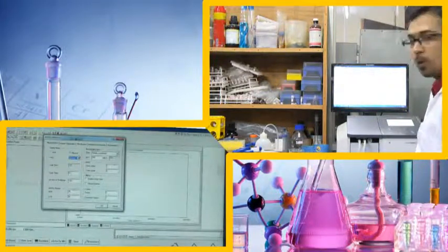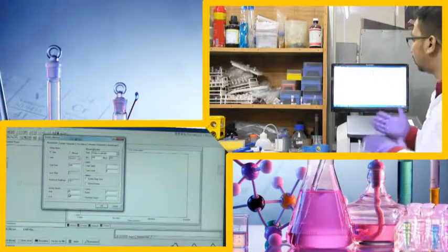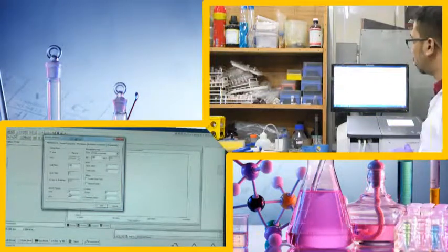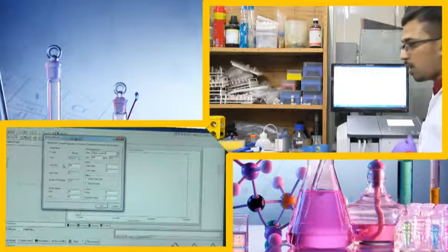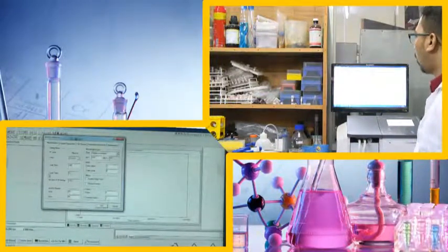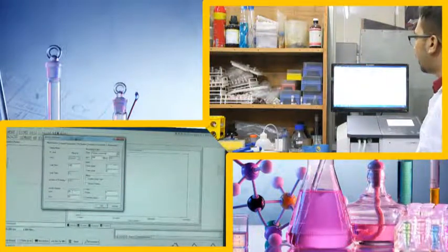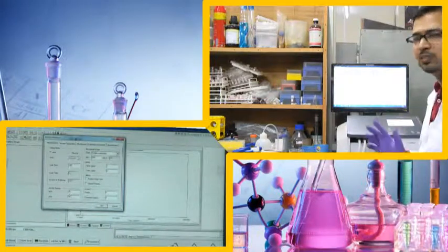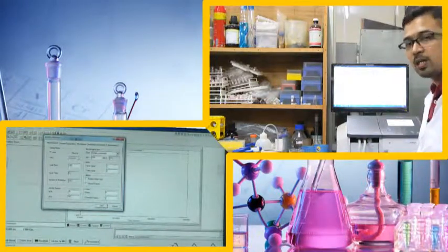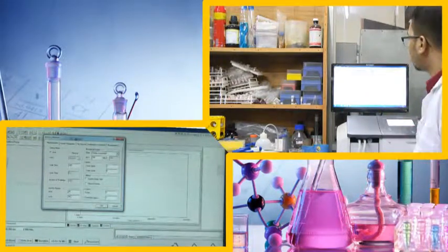However, we are not going into manual, we will stick to auto, and the total time out here will be 5 minutes, which is basically 300 seconds. So, here the units are second and total time is 300. We are not bothering with the cycle time and number of readings here, and the activated region is 20 and 40, that is 20 second to 40 second. These are by default, but however, you can change them once you start with the experiment. We will show you later on.